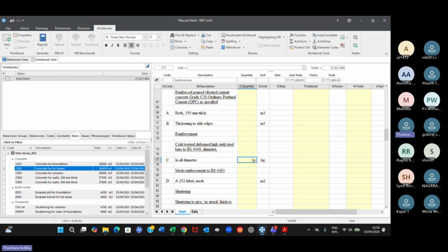But if you want to use some ratios, let's say 200 kilograms per cubic meter for slabs and 150 for, now when you work as a quantity surveyor, especially a consultancy quantity surveyor in a consultancy firm, they will do some sample calculation when we prepare the BOQ, because you will not be able to do very accurate calculation on reinforcement when you prepare a BOQ,